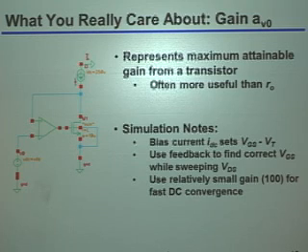I basically am going to bias my device with some given bias current, which, by the way, you're going to calculate exactly using the procedure that we calculated before, right? Meaning using the load cap, the gain bandwidth, and V star. And then what I'm going to do is place this ideal amplifier in here so that I can change this VDS so that through the feedback, it'll basically control the drain to source voltage across the device.